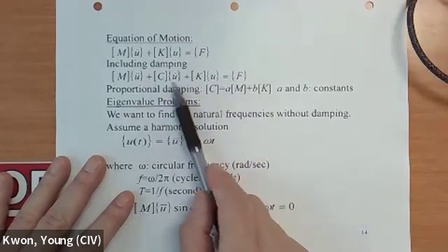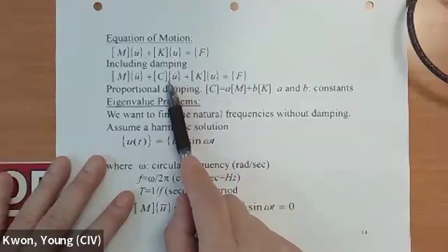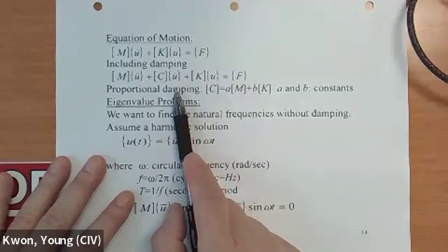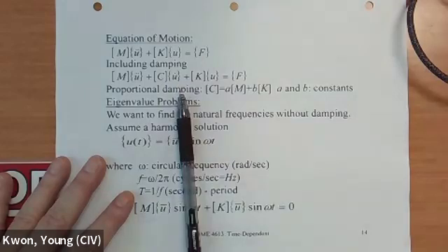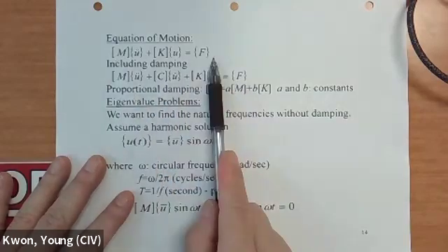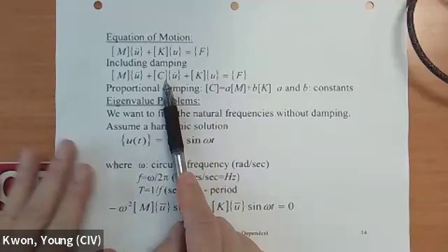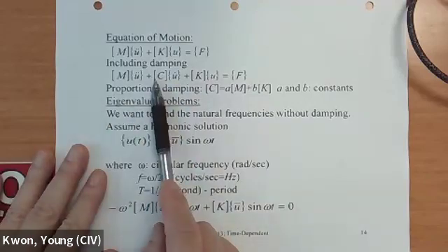And again, the simplest damping term is this kind of viscous damping, so the damping force is proportional to velocity. If you look at a door, some doors don't have a damper, and some doors have a damper so you cannot open them so quickly. Those dampers are like a viscous damper, so the damping force is proportional to the velocity of opening the door. Anyhow, this is the more general equation, and this is the equation when you neglect the damping. Many times people ignore damping. Of course, sometimes damping is important, but sometimes we ignore it.